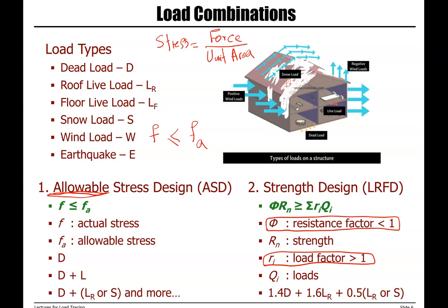So the load factors here, and you see, instead of just adding all of our loads together, we multiply each load by a load factor, and then we add them together. So each load has a load factor, and we multiply our strength by a resistance factor.